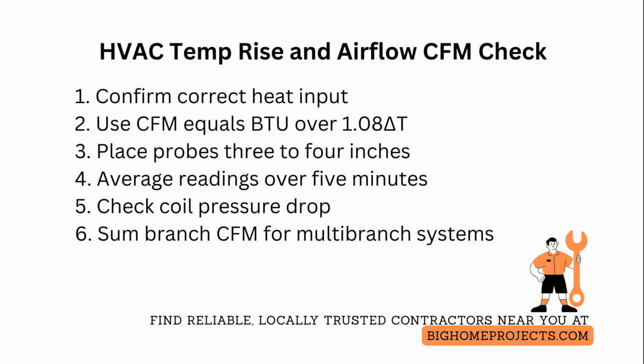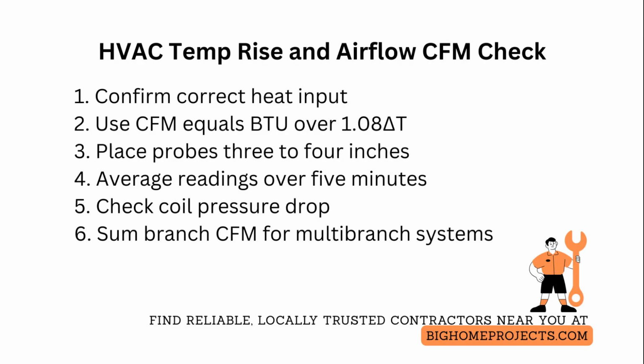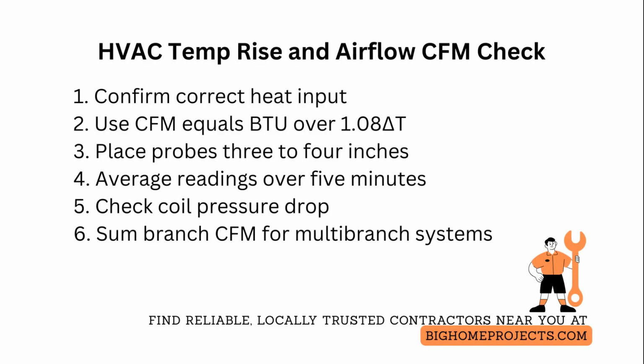When measuring temperatures, place high-quality thermistors or thermocouples 3 to 4 inches into the center of the airstream on both supply and return and average multiple readings over 5 minutes to avoid transient stratification. Account for filter and coil pressure drop.